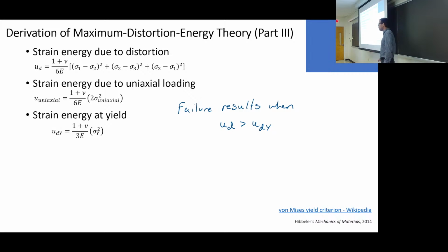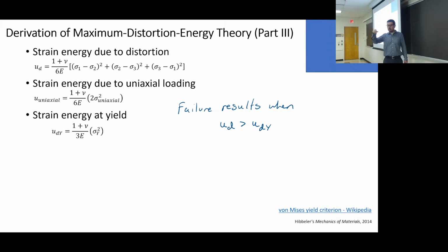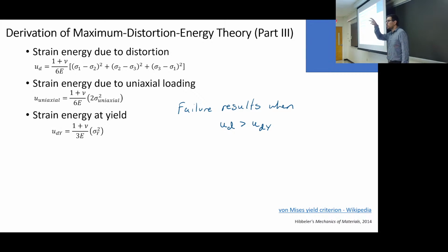Do you have to do this derivation ever again? Not in this class, maybe in another class. Should you write these equations down? No. I'll show you the ones that you want to write down on the next slide. But the concept is powerful. The concept is taking what we talked about with strain energy density before. It's introducing this idea that there can be a set of stresses that create distortion, and that we can separate the overall strain energy density from the distortional strain energy density.